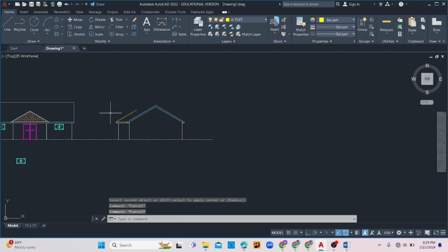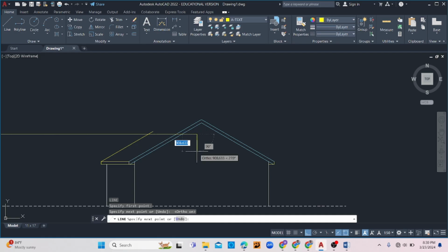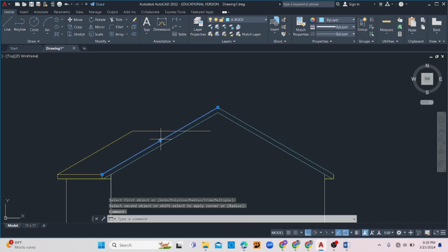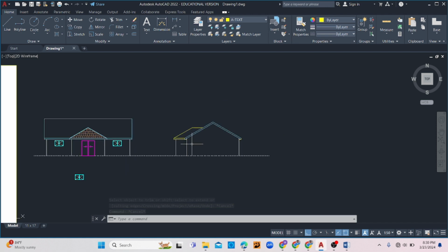Now in terms of the gable porch, the hip portion, we can capture that height from what is over here. Project our line across and see where it falls. So it basically falls up here. So let's fillet the corners, fillet here and here, and then trim out whatever is not a part of it. Alright. So just like that, we have fixed our error very easily.